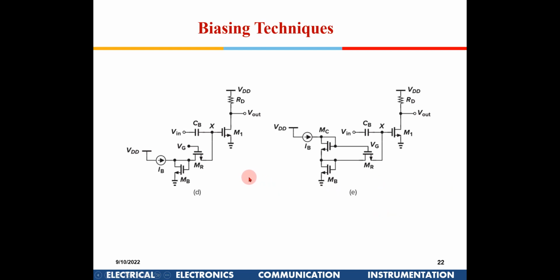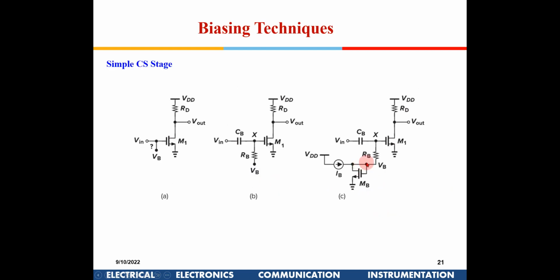Okay. So can I repeat why we are using RB? If you don't use RB, this MB transistor, the biasing transistor, generally we keep W very large. If you keep W very large out here, you will find this is adding a direct capacitance at this node, which could affect your high frequency operations, because that capacitance will short circuit your high frequencies. So at high frequencies, I don't want the signal to be attenuated, so I will keep an RB in between. Is it okay? Okay, sir.